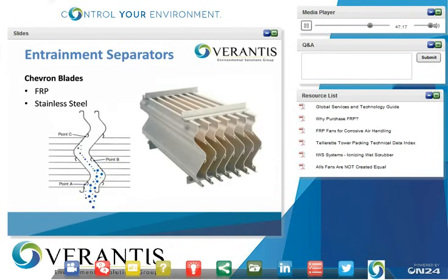Third type, which is very common for us here, is a chevron-style blade. These can be manufactured out of either FRP or stainless. We can also manufacture out of high nickel alloys if needed, depending on the situation. The orientation for these is really important. Both the pictures on the left and on the right show the orientation of the hooks downward. The little bubbles there, or dots, represent the water that's being carried up in the airstream. These are much less likely to foul like a mesh pad, although the little hooks that are in there can develop a buildup of materials. So these should also be part of the routine maintenance and inspection to make sure that they're performing properly and there's not too much buildup inside the hooks.